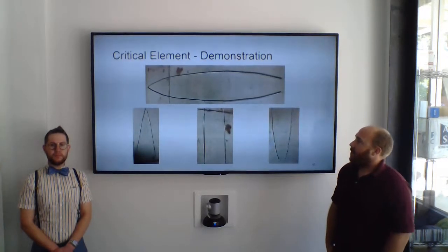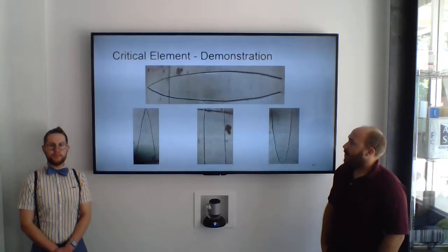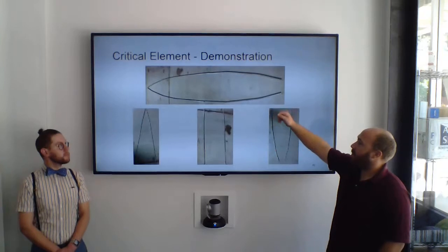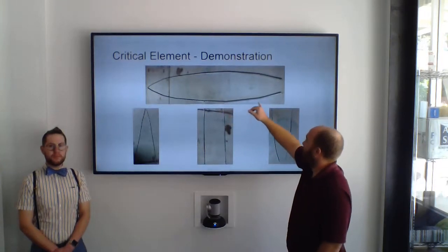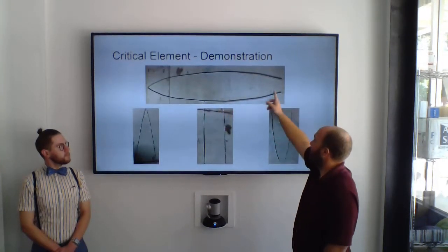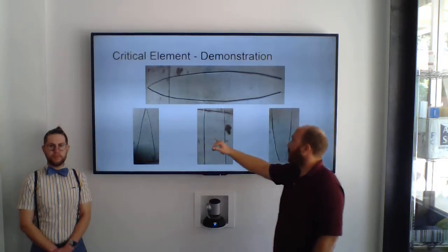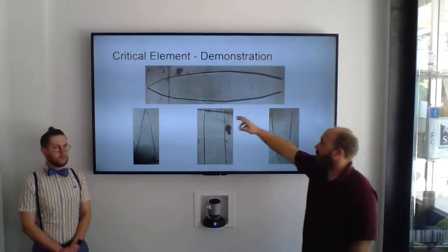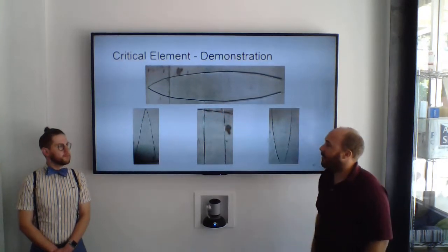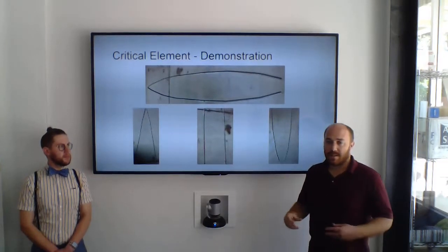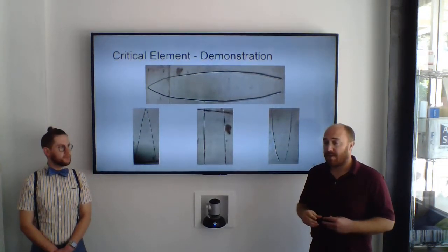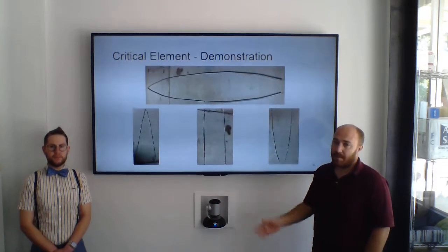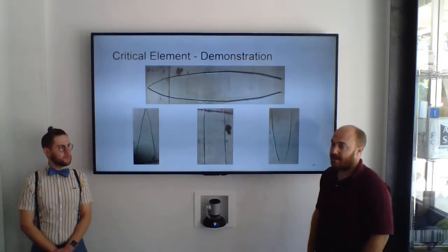So for our critical element, we were discussing with Professor Kosaraju, and he recommended we shape the frame of our kayak. As you can see here from the top, we were able to bend the aluminum tubing to make the lower part of the frame. This would be the front part, the middle part, and the lower part as seen above. In between these tubings where the tubes will actually meet, we're going to have a solid piece of aluminum that's going to slide inside of each tube snugly. And with that installed, we'll be able to handle the stresses that the kayak will endure.